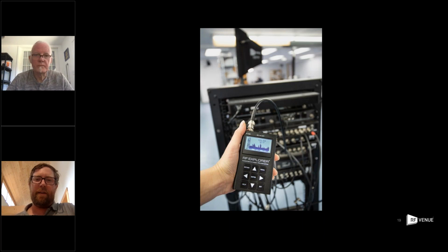And one of the things that folks are generally not very aware of is that when you have just the whip antenna, a little UHF whip that ships with the unit, similar to any other whip antenna you'd see on wireless mics, you're not seeing the same thing that the rest of your mic receivers are seeing, at least in this photo.